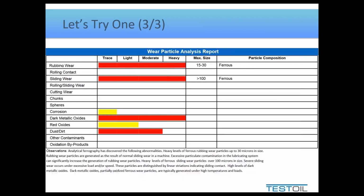When we get to the last part of the report, and I didn't bother including the pictures, I was just looking at the data here, we've got our analytical ferrography. Now, when we look at the analytical ferrography, the first two rows, rubbing wear and rolling contact wear, are typically considered to be normal wear mechanisms. However, the size of particulate always plays a key role here. And what I'm seeing is some fairly large size particles contributing to the high or heavy amount of rubbing wear.